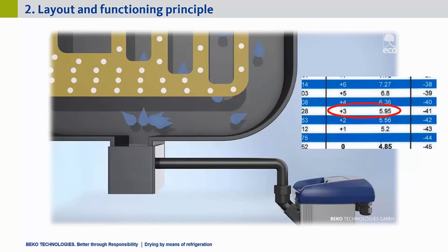In our example, the air has now eliminated any excess water and contains only about 6 grams per cubic meter of water vapor. But the air is also very cold, namely these 3 degrees Celsius. And therefore, with this amount of water vapor in the air at 3 degrees Celsius, we are at our maximum absorption capacity for water. This means that the air is saturated or has 100% relative humidity. And thus, the air is of course everything but not dry at all.